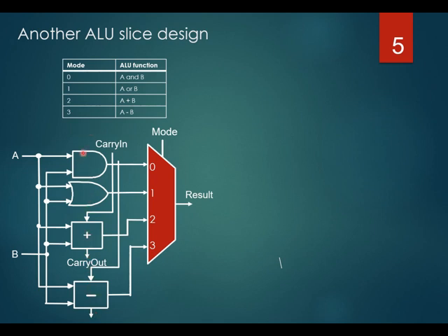Together, at one time, we just need one of them to work. So why do we need so many units? Because at one time we only need one unit. So if we can share those units, then we better share them for optimization purposes. An AND gate cannot be shared with an OR gate because they are totally different gates.